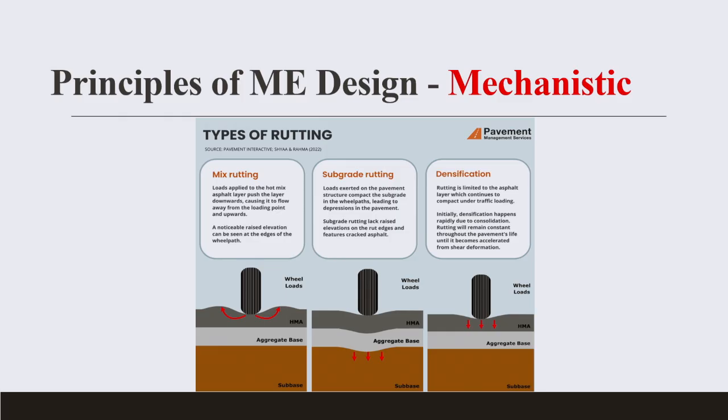For those who are into design. Yes. In the last 4 years, I've been to so many projects, and I discovered that the pavement design fails as a result of the fact that they assume uniform CBR. Take Abuja to Kano, for instance. When the CBR was conducted initially, some areas were above 10, some above 15. But in design, they assume a particular value. And this has resulted in failure. You see, unsuitables, sometimes within the range of 300 meters, 200 meters, you will notice a failure on unsuitable material.